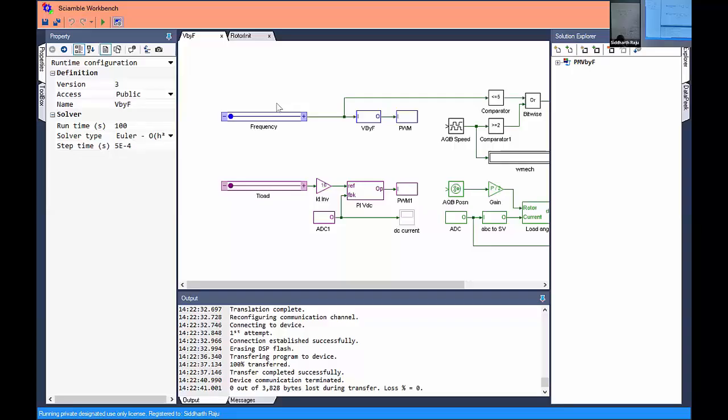Why not? The load isn't synchronous with it. Perfect. So in our equation right there on the right, the tau net, if alpha is 0, then the net torque is sine omega t, which is just varying sinusoidally. So there will be no net torque and the rotor will not start rotating. So I need to start off with very low frequency so that the rotor alpha can catch up with whatever speed at which the stator space vector is rotating.